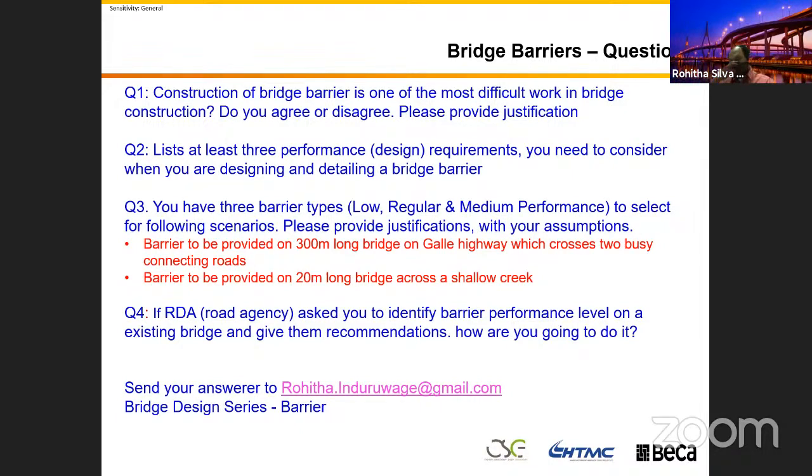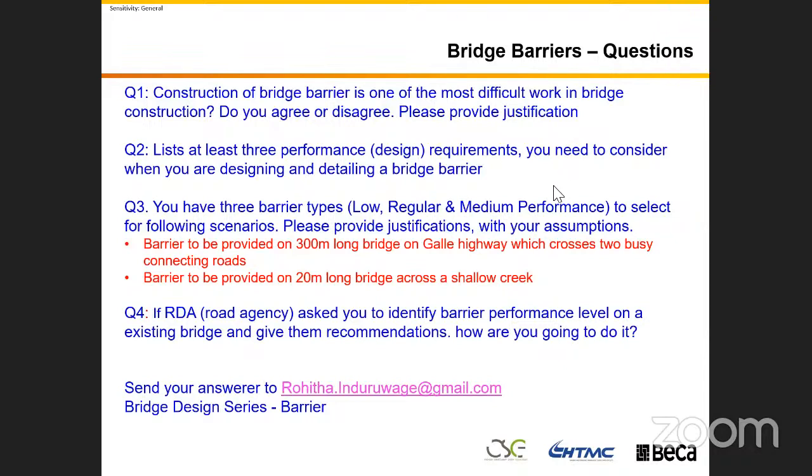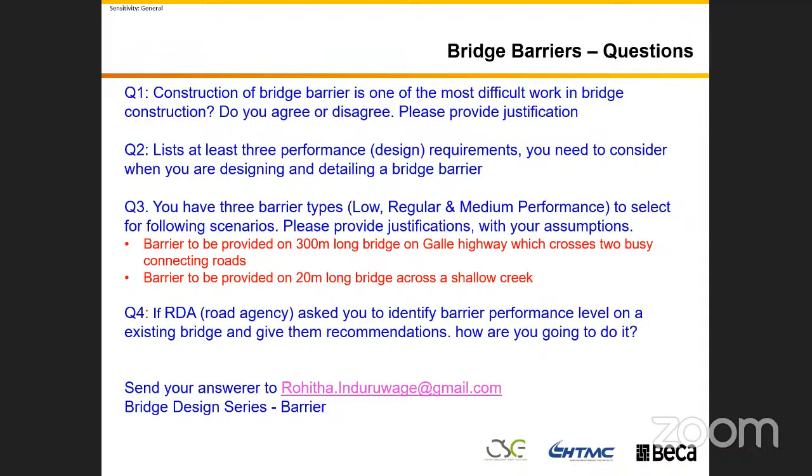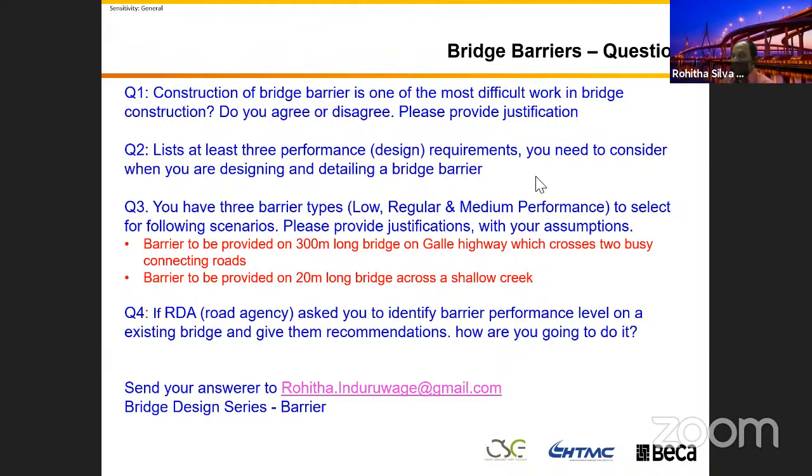But in some places, I remember we had something like 17, 18 meters deep from the top of the pile, so we had to drill through and grout it again. Okay, thanks, interesting. So that's the one where you put those tubes through the pile and do the testing, isn't it? Yes, the sonic logging. We'll be interested to hear about it. Okay, I'll let you continue. Thanks, Chanaka. Thank you so much.